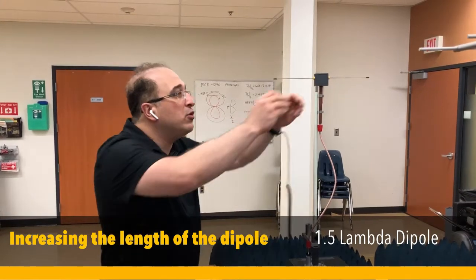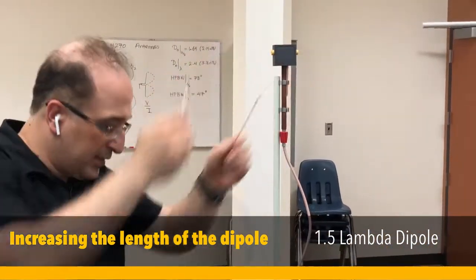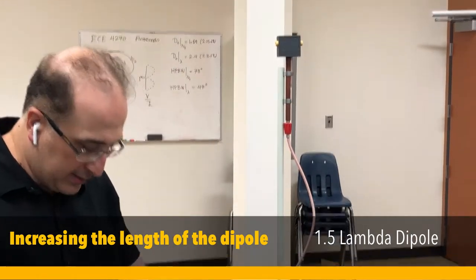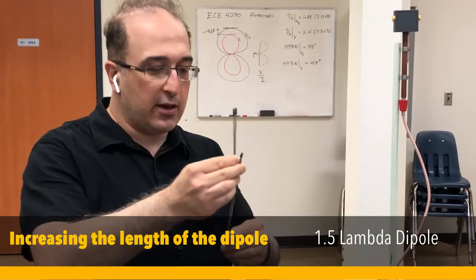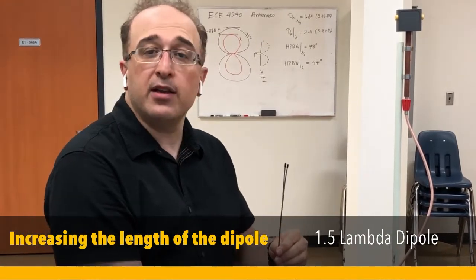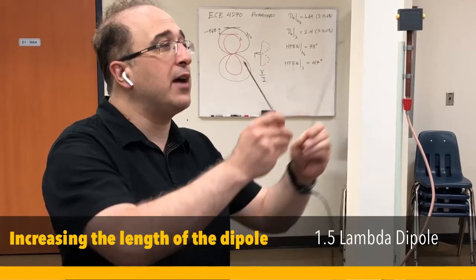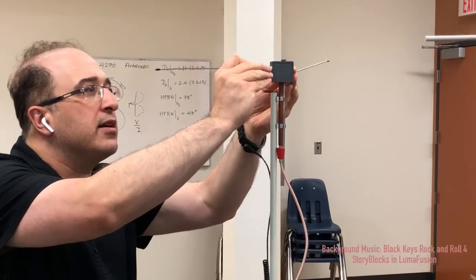So I'm going to remove this arm and this arm, and this was an arm for the 1 lambda dipole antenna. I'm going to use bigger arms now to make it 3 lambda divided by 2. 1.5 lambda now would be the length of the dipole antenna.